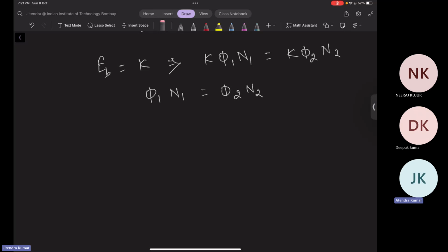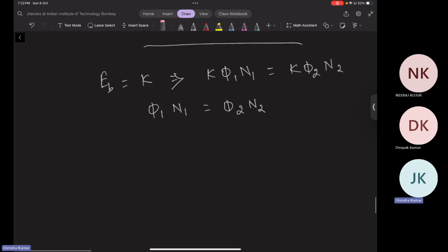But if you are conscious enough, everyone has to pay attention in the exam questions so that we do not commit any mistake. Otherwise, only three equations are there in this machine, right? Torque is equal to K phi Ia, back EMF is equal to K phi omega, and one KVL. But with only these three expressions, we can derive so many things and make so many manipulations.